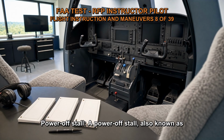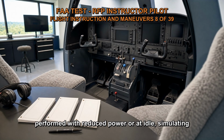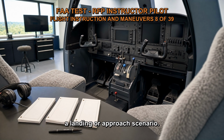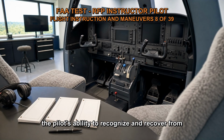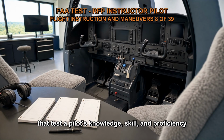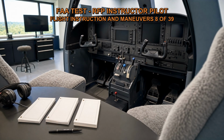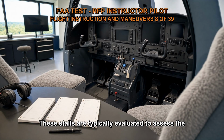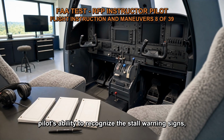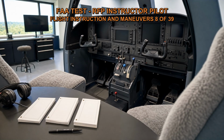Power-off stall. A power-off stall, also known as an approach-to-landing stall or landing configuration stall, is performed with reduced power or at idle, simulating a landing or approach scenario. The purpose of this stall is to evaluate the pilot's ability to recognize and recover from a stall while in the landing configuration. Both power-on and power-off stalls are critical maneuvers that test a pilot's knowledge, skill, and proficiency in recognizing and recovering from stalls in different flight conditions. These stalls are typically evaluated to assess the pilot's ability to recognize the stall warning signs, take appropriate recovery actions, and maintain control of the aircraft throughout the maneuver.